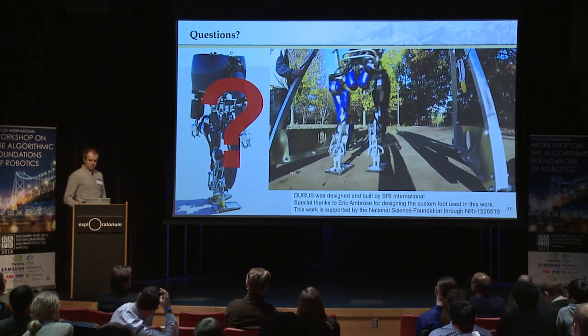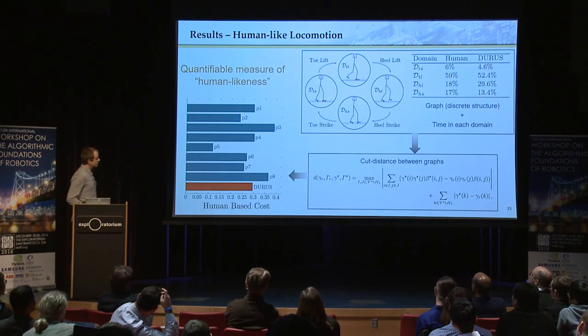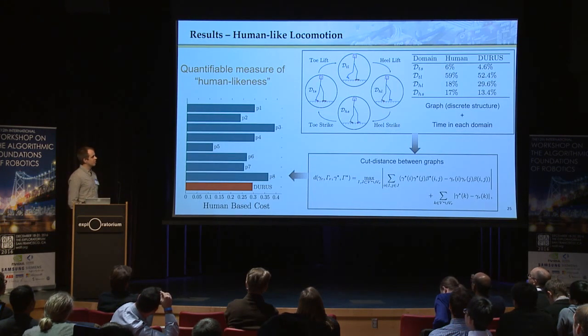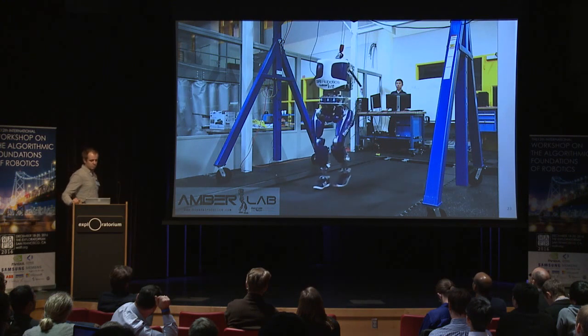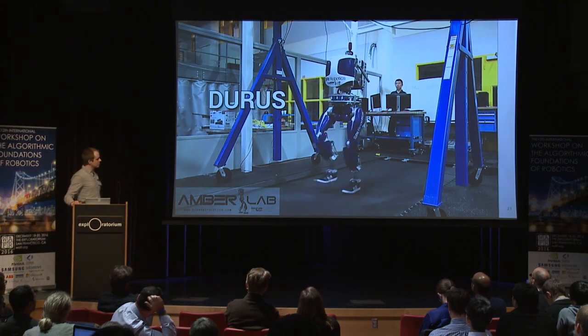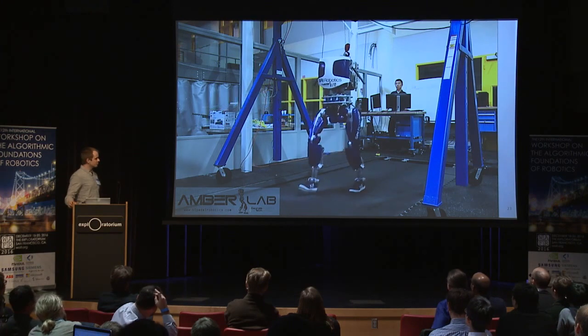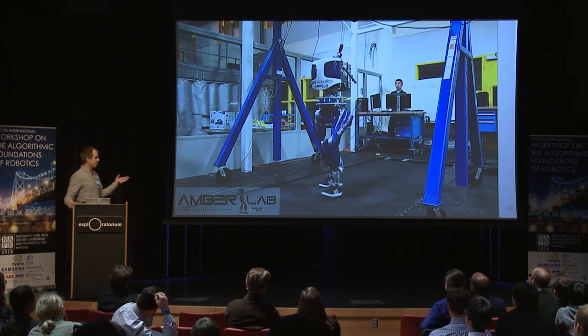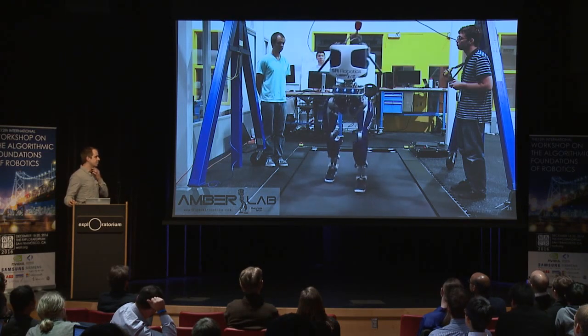So the walking gait that we designed, in theory, will have this push off. And we saw that a few times throughout the experiment, but I agree that in the video we have here, the robot was beginning to cycle or oscillate forward and back sometimes, so it's not as prevalent as what we see in the simulation. When we were designing the walking gait, we were trying to leverage that domain towards energy efficiency as much as we could.